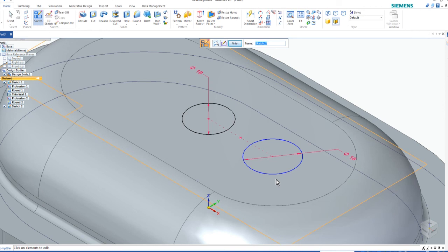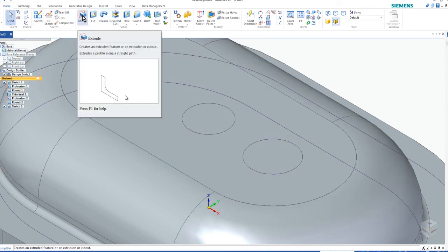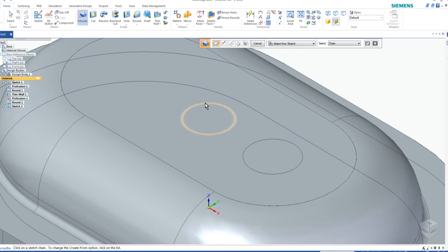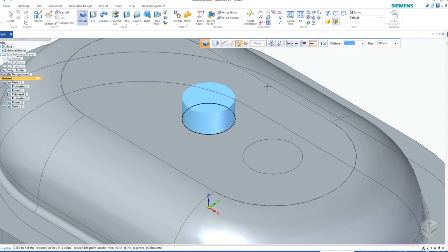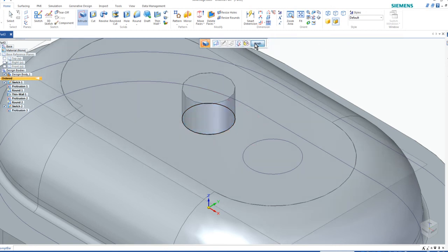Let's zoom in, finish, and cancel. We're going to use a straight extrusion. We're going to select that, enter, and we want this to go a total of 11 millimeters. So we're going to type in 11, enter, pick, and finish. The 11 millimeters comes from, again, the section view, which shows where the length of that connector goes to. It's right smack dab in the middle.